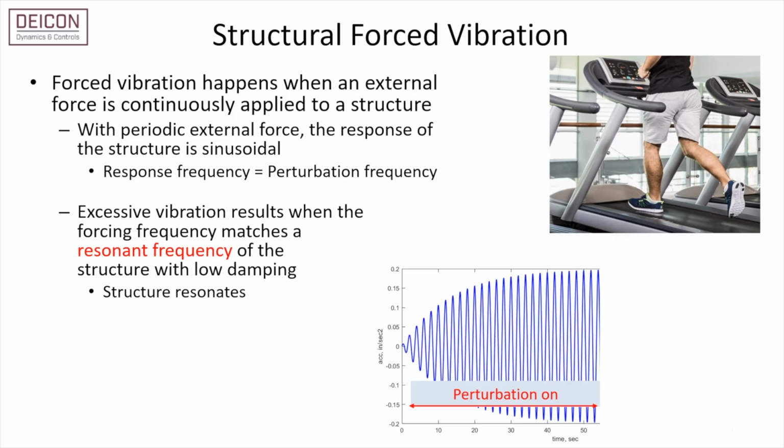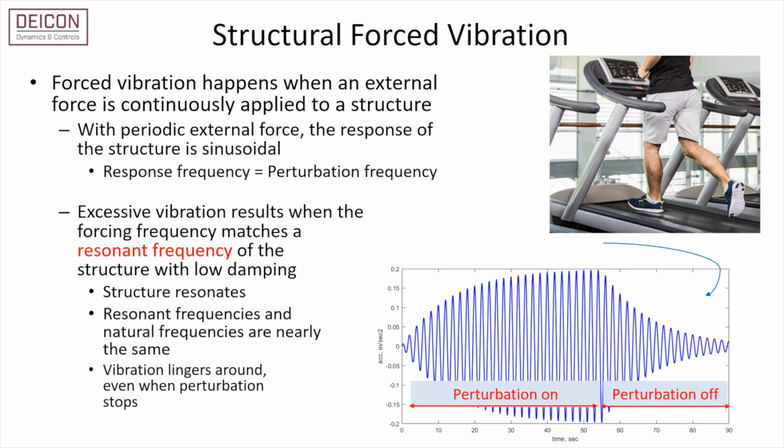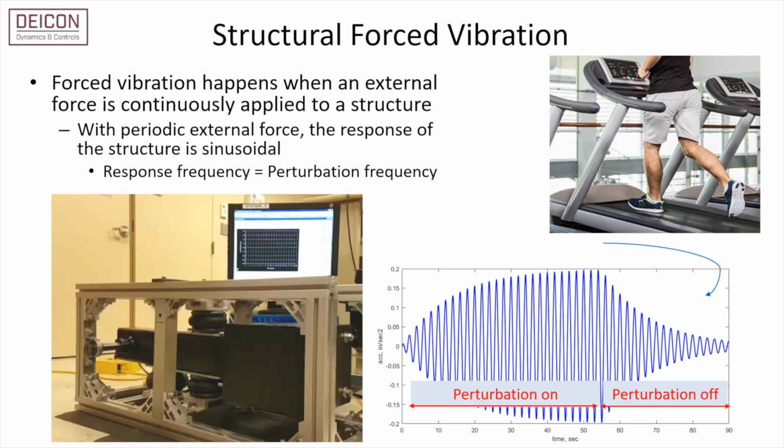The frequencies of resonant vibration are called resonant frequencies, which are almost the same as natural frequencies in structures with low damping. When the external force causing resonance ceases, the structure doesn't immediately stop vibrating. Instead, it enters the free vibration phase, during which the structure continues to vibrate, but in a decaying fashion. This demonstration illustrates the buildup of resonant vibration, followed by the lingering decay of free vibration in a structure with low damping.